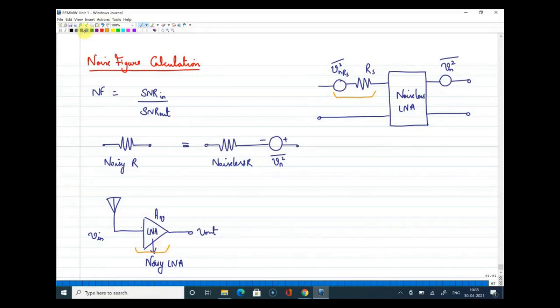And now on this side, I'll mark the actual input coming to this LNA as V. This is the output, and the gain of this LNA is represented as AV. So what I'm going to do now is, for a single stage, considering an amplifier stage attached to an antenna, evaluate the noise figure of this circuit block. So carefully look at the steps of how we are going to estimate the noise figure of this circuit block, an antenna and an LNA in series.